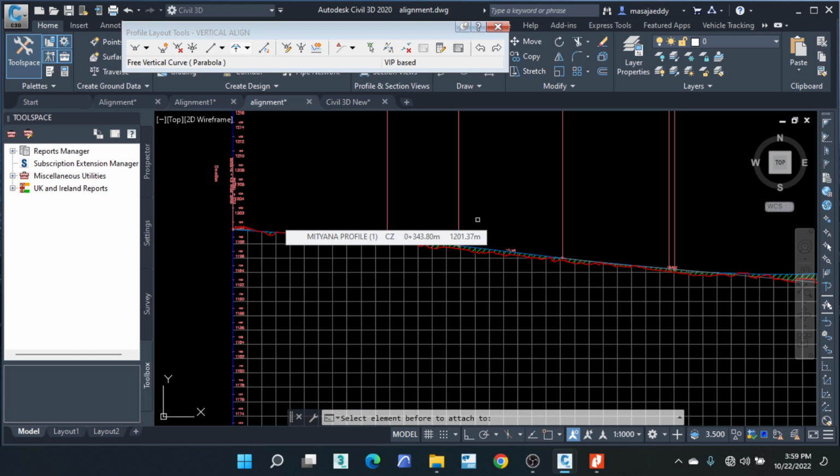And then you provide remedial measures such as signs for reducing speed, speed humps, and maybe chevron road signs. When you find them on the road, maybe it is a very sharp curve and there is what we call a design departure. So you insert them on the vertical curve. The message is reduce speed, or they provide road humps to slow down the traffic.